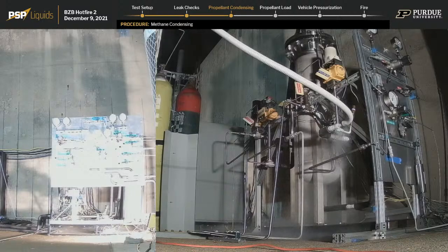The next thing I guess we should talk about is why we have a valve next to every manual regulator, and what that's kind of telling us. Yeah, so when we have a valve next to every regulator, that lets us really isolate the system and make sure that flow doesn't ever go back. It's very important to us that we isolate things with check valves to make sure that flow only goes one way when it needs to.